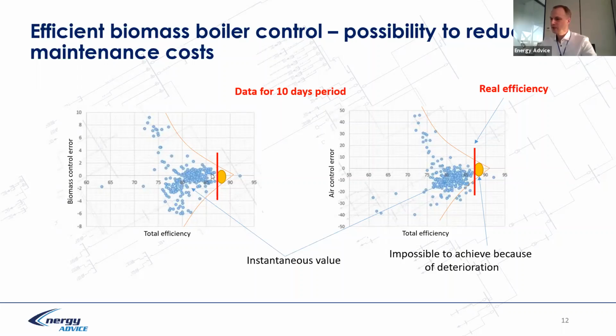And if we do not operate the boiler like that, we can extend our boiler operation until the next maintenance activities. And also, it's money in savings. To understand what 75 to 85, a 10% efficiency variation, means: this means 1 month of fuel savings. 1 month of fuel savings.